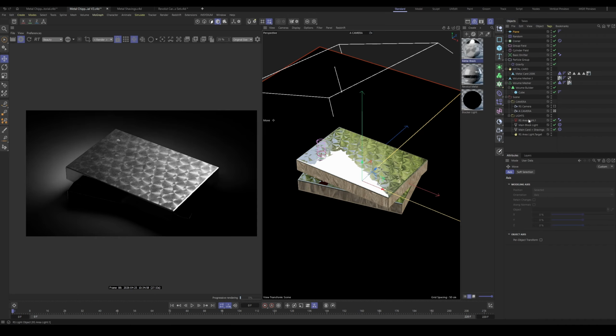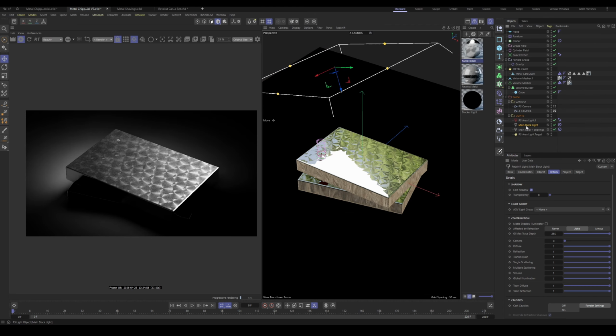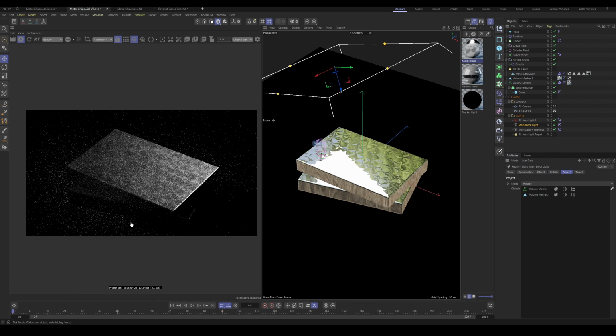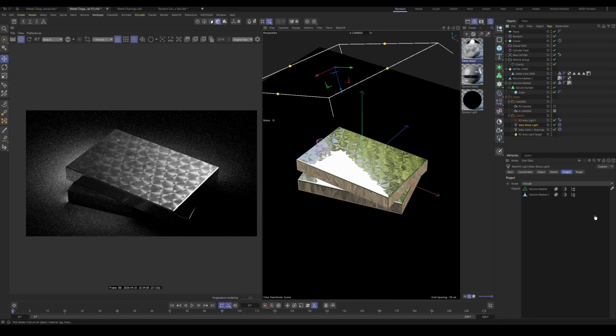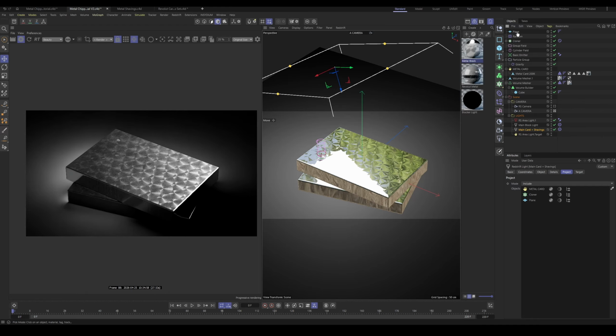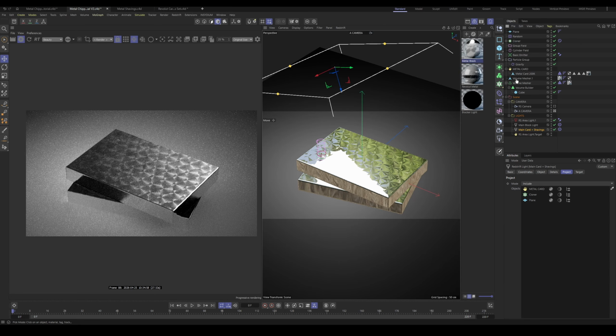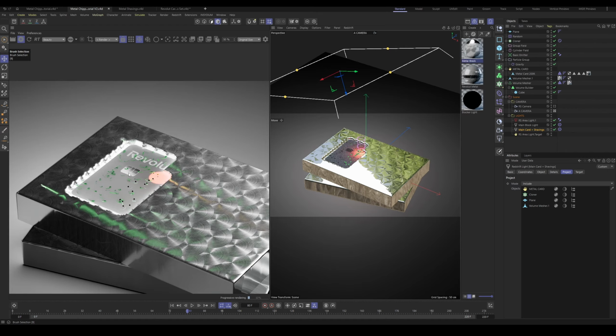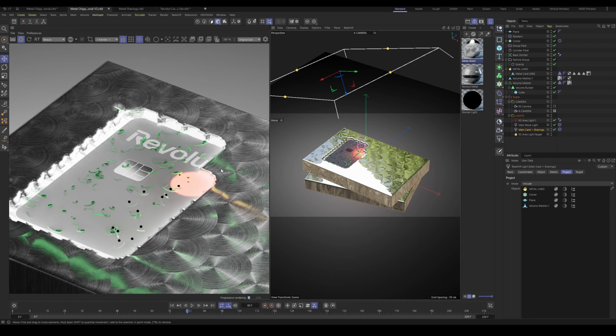So what we could do is, in our main block light, we'll go to project, and we'll add in our volume measure.1, which is our block that's underneath. And then in our main card plus shavings, maybe we could add our floor, and we could probably add our volume measure.1 as well. Yeah, which helps ground this. Now you can see with our effect setup, our metal shavings are still green. I think they're inheriting the particle color.